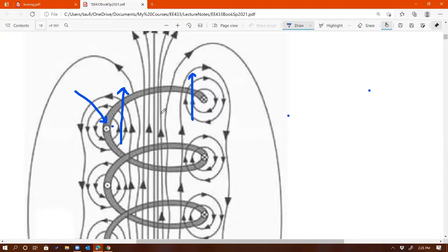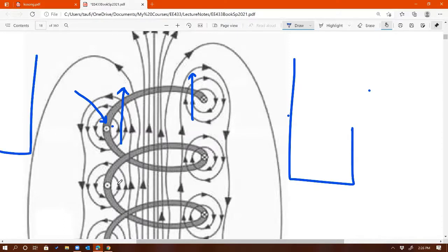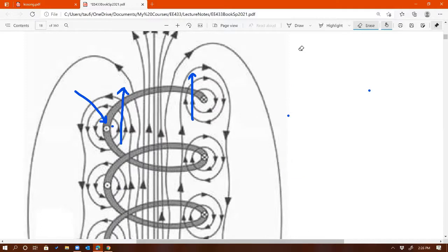Well, because we're going to place our magnetic material inside. By having this arrangement of wire formed into a coil like this, we are effectively producing flux that is concentrating inside the coil. If you look inside the coil, that's where we're going to place the core. The flux is the most dense in the center of this coil. You agree with that? And that's good, because that's where we're going to place our core. We're not going to place the core here or there. We're going to place the core inside this coil. In fact, we wrap this coil around that core. So we are putting a lot of flux in the center of the core, and that could be achieved effectively by making a coil, a simple arrangement like this.